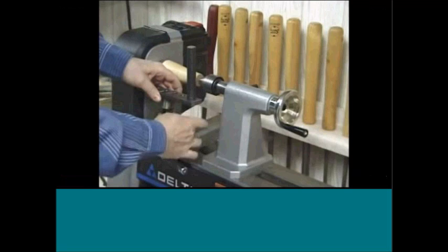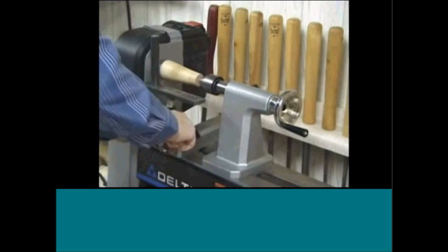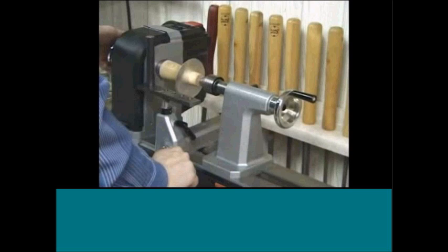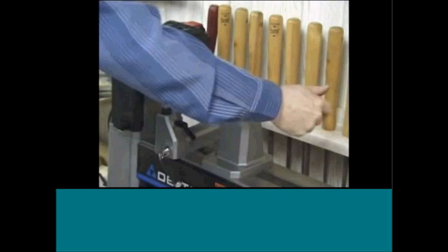The tool rest has a stop collar for height and a flap milled into it so it can't rotate. A method for centering the aluminum disc is to slightly release pressure on the tailstock while carefully pressing the wood support into the disc while it's spinning, and then tighten the tailstock, pressing on the support blank to hold the disc.